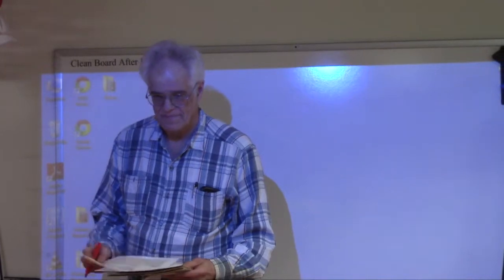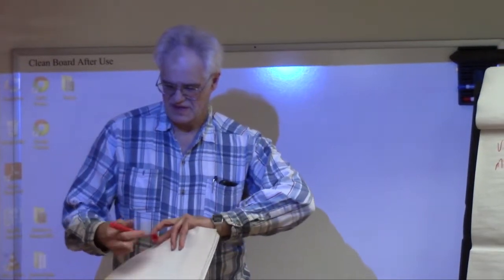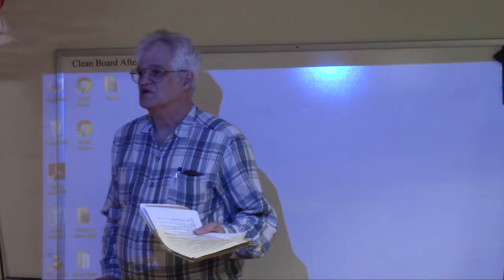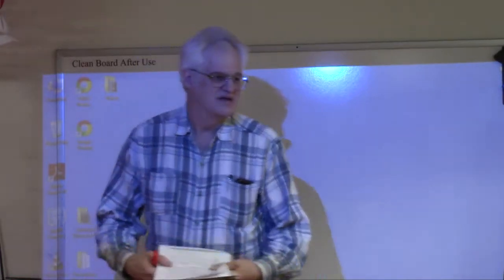What about squelch? As in life, there's generally either natural or man-made noise out there, electrical noise. So when you're sitting there listening to a frequency with no carrier transmission on it, you're going to hear noise, right?